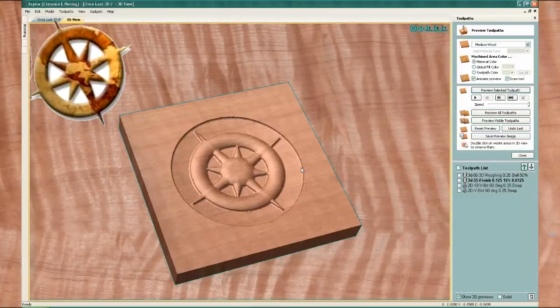The edge of the bowl is a little over a 1/16 of an inch deep, which I consider to be acceptable. It's kind of nice to lose some wood off the top of your 3D image in case the rough board is not quite level. If you take off a 1/16 of an inch or so, you'll end up with fresh wood, newly cut, so it has a consistent look.